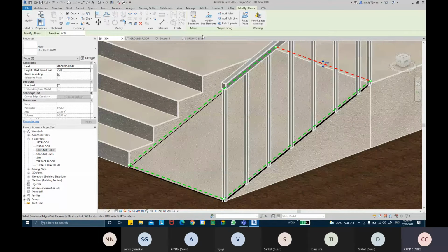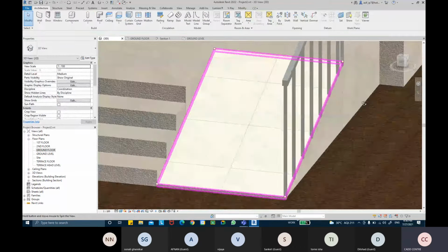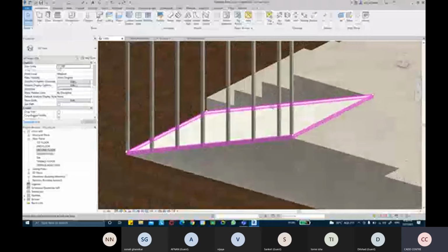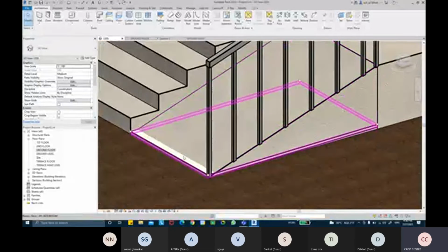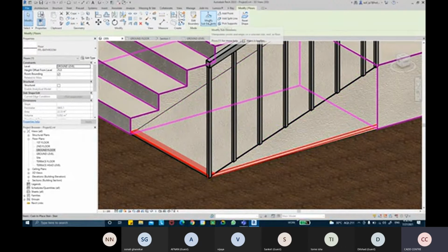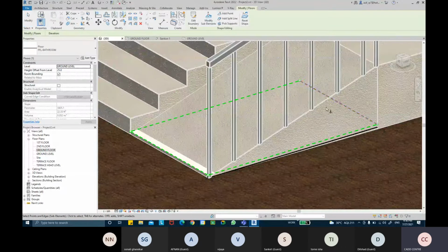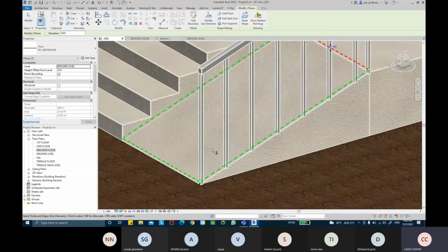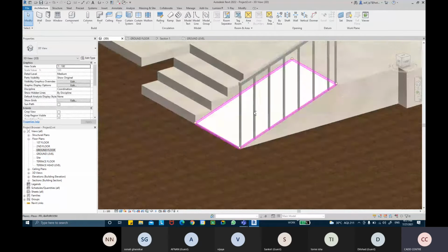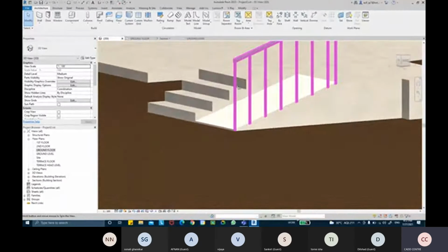Here you go. Yeah, so simply select that ramp, take the modify sub element, select that line, and over here you can type the height that it should incline, 600 mm. So that's at 600, this line is at 0. So that's inclined, like a slope. Yeah, like a slope only it is.